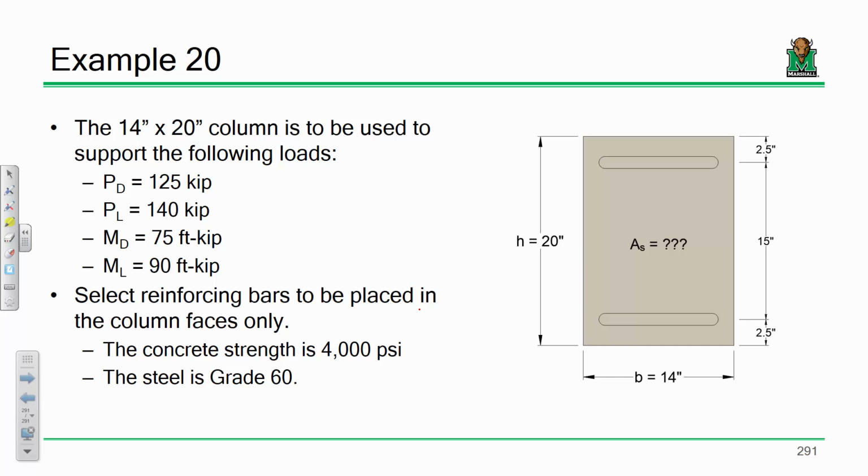Now, how do you determine gamma? Look at this. Say it again. The rebar. No, it'd be 20 over 15. Or, no, it'd be the opposite. It'd be 15 over 20. What is 15 over 20? Say it again. It's 0.75. So which one do you need? You need the value from the 0.7 chart and the value from the 0.8 chart, and then you average them. Hold on. Hence why I gave you the 0.7 chart and the 0.8 chart. We're just going to use both charts, interpolate, go from there.